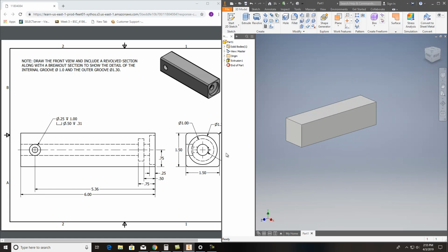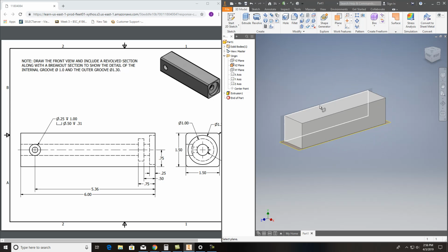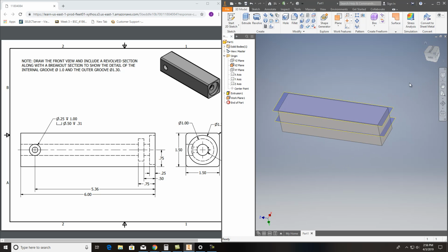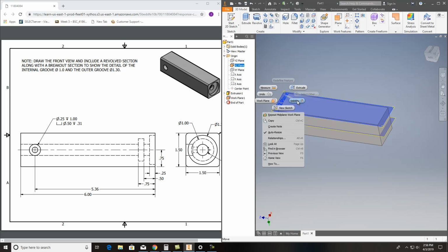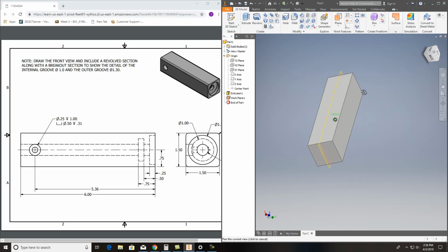And now what I want to do is cut all these internal parts out and then revolve it. I'll show you how to do that. It's pretty cool. But what I would do is, let me look at my planes. I'd use that plane, and I'm just going to make it current by right-clicking on it and going to Visibility. And I want to go Plane, and I want to find the midpoint between two planes. I'll go between here, and I'll hit this one. I really didn't even need the visibility on my XY plane, so I want to turn that off. All I did was hit plane, midpoint between two planes, hit this surface and the other surface, and it put me in there.